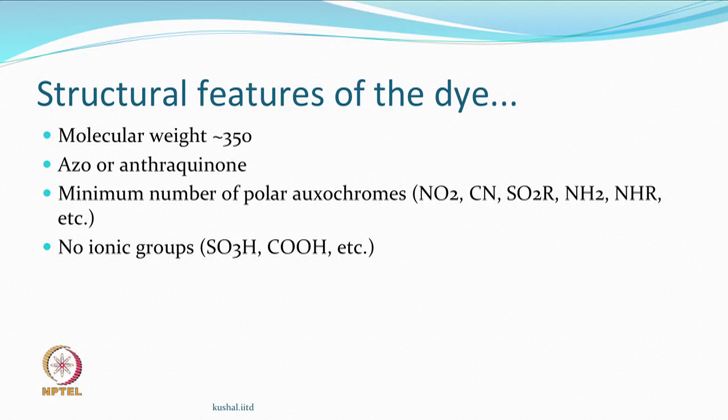So, some other things, which obviously are based on the experiments that people have done: if the molecular weight is very high, then it is also a high energy dye. If it is very low, in the range of 200s, 250s, then again it is low. So, somewhere in the moderate range of around 350, not exactly a number, around this, people may like to have a molecule of this size.